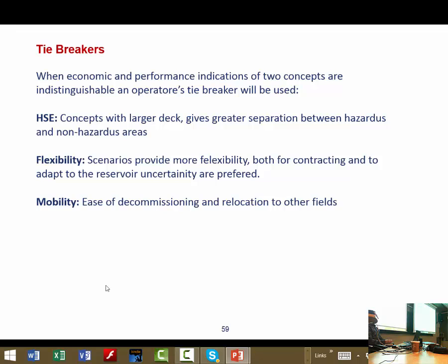But sometimes you have a ballast system, so you have people dealing with the marine part of it. Yes, of course, the ballast system and the anchor system. When we offload, the unit will be completely empty, and the draft will be quite low, which is not stable. Then we have to fill the ballast tanks to increase the draft to a safe level. And if a storm comes, do you also have to ballast it more?